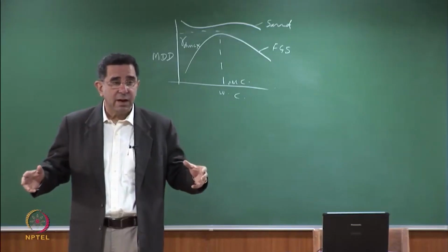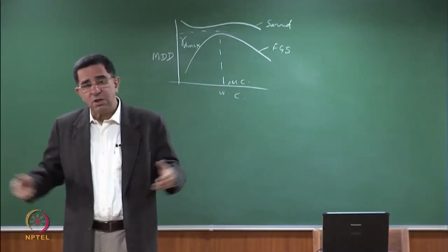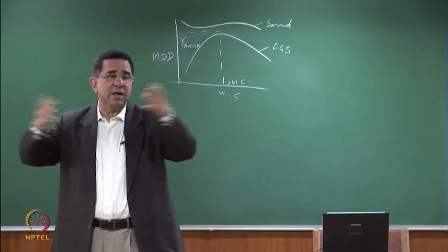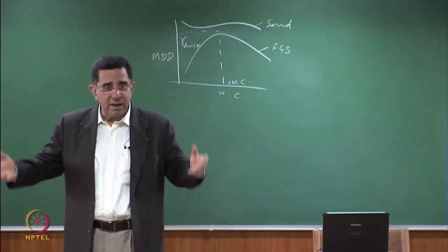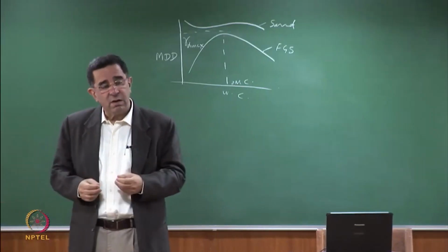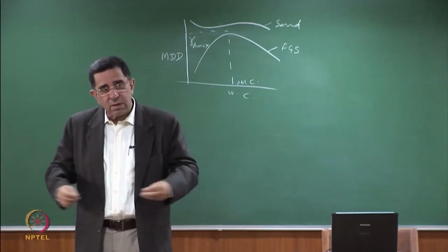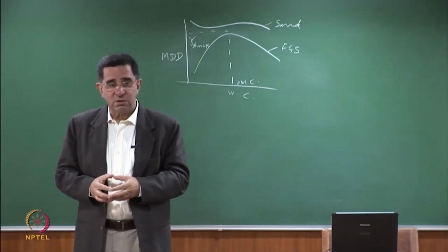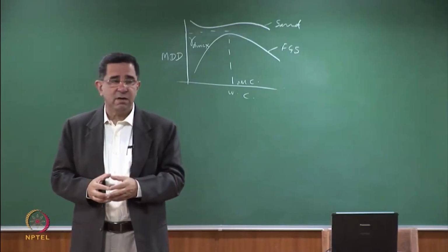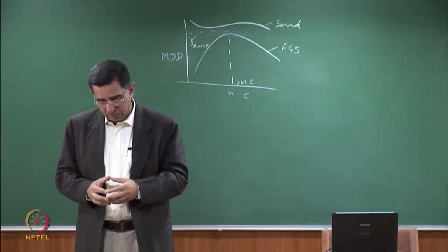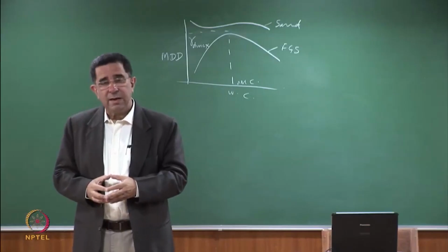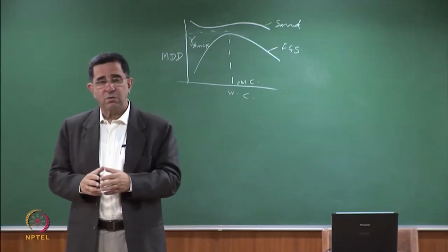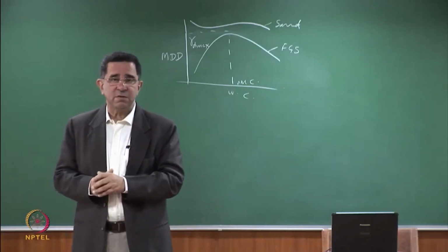the ash pond. But now, taking a holistic view, including the elevation of the water table level, because once you make an ash pond, you are creating a big lake. That lake may lift the level of the water table. Now they have started to prescribe liners for ash ponds as well, and we'll address that in the design of ponds. And as far as erodibility is concerned, dust or water erosion, we will look at it when we design embankments using ash.